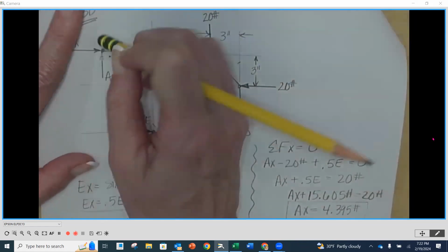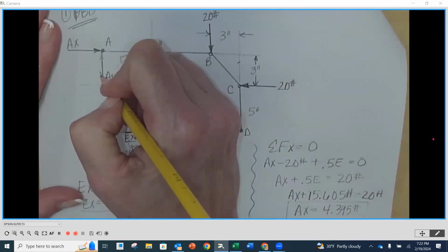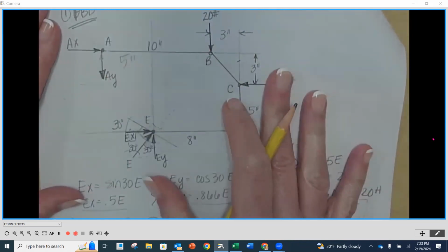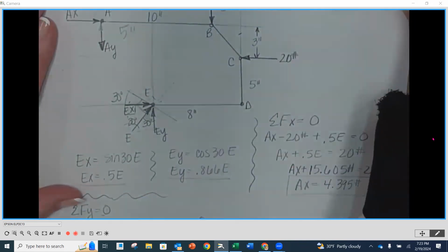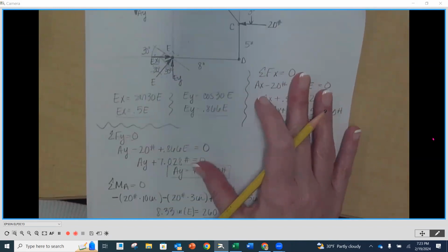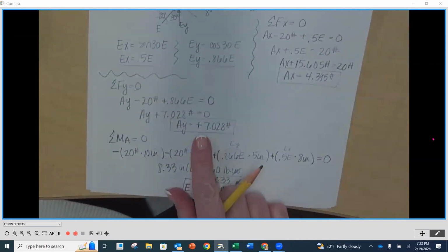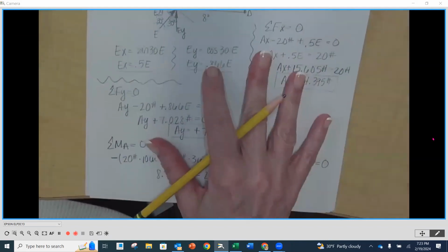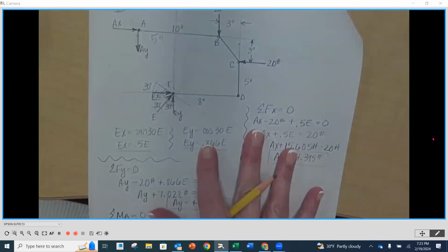We're going to erase that direction, and we're going to show it going down. I check your final diagrams to be the correct direction. So if you need to make those adjustments, you don't have to recalculate to confirm it. We just do that 2-part process because that's the only difference. So make sure that you make that 7.028 positive and change the direction to down for AY.